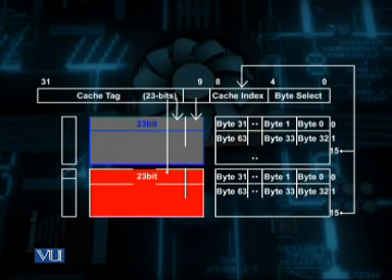You can see that this arrangement has 16 blocks in each set. Therefore, an index field of 4 bits and a tag field of 23 bits is associated with each element of the set. This shows that as the associativity increases, in this example from one-way to two-way associative cache, the index field decreases and the tag field increases.